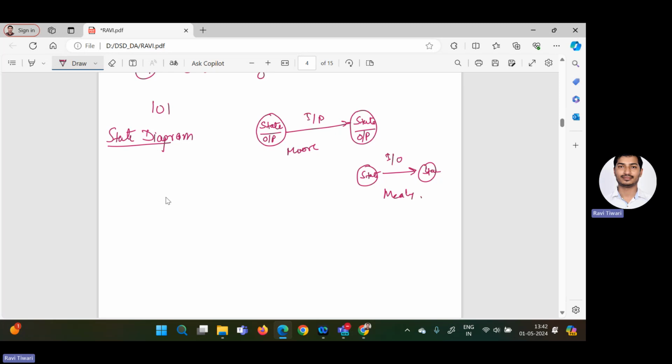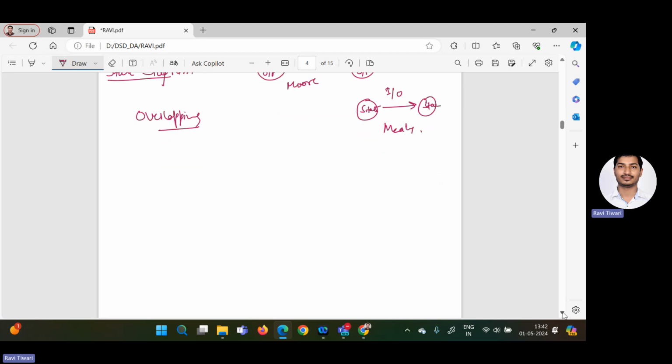Let's start a state diagram for 101 in the case of overlapping. So always we initialize the state diagram from state A, and we write down the output along with it. So this is the state A and the output is 0. It's the initial condition, and we are detecting 101. We have not received the correct pattern. If we receive a single bit correct, then I will move to another state B. So here you write down input is 1 and this is the output 0. Why? Because we have not received the correct pattern till now.